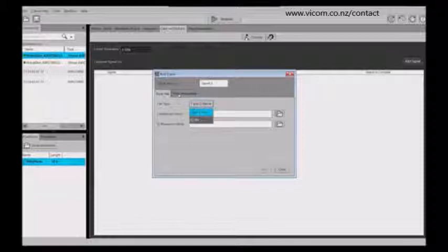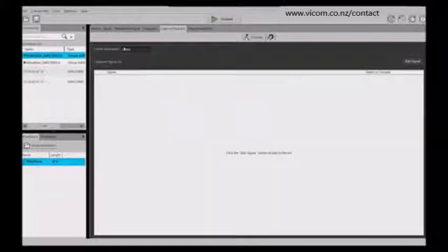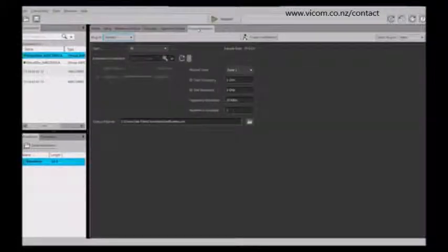Then you basically specify the frequency that you want your carrier to run at. So this is our capture playback capability. You can capture waveforms or signals from a real-time spectrum analyzer or from an oscilloscope and then play them back. Precompensation is our tool for enabling you to create waveforms, removing the loss of the sin X over X response of the AWG.